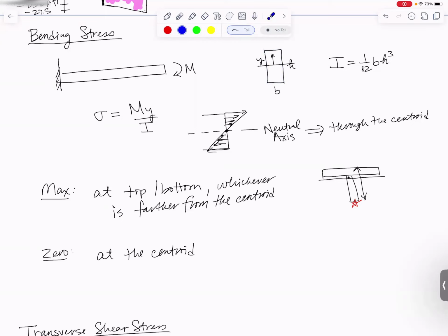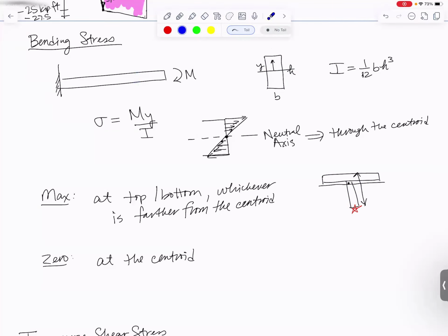and turn it and look at that end, what shape do I see as I cut it open at a section? And we usually draw that much larger because this base and this height are small distances measured in either inches or millimeters versus the length of the beam that might have been measured in feet or meters. And similarly, this T shape is an alternative kind of cross section you might see if you cut open the beam. So you'll oftentimes with these problems see both a beam and a cross section. They are related to each other. One's looking at the side, the other one's looking at the end.